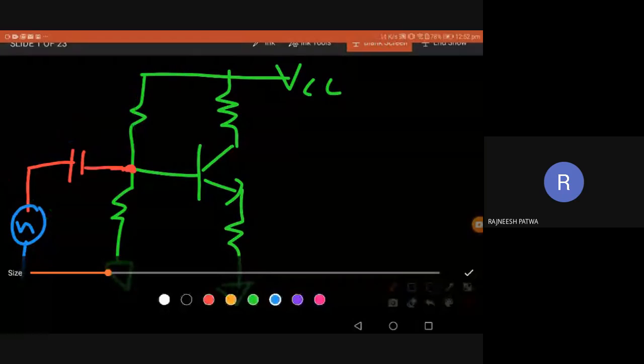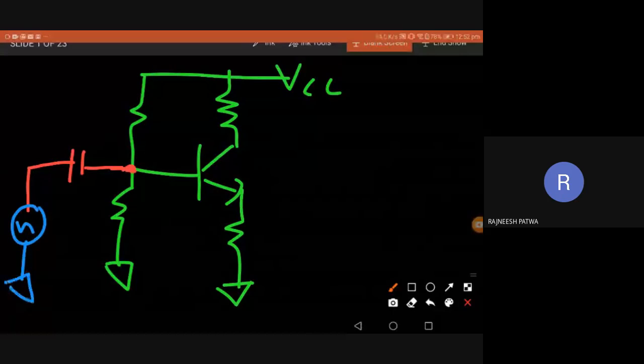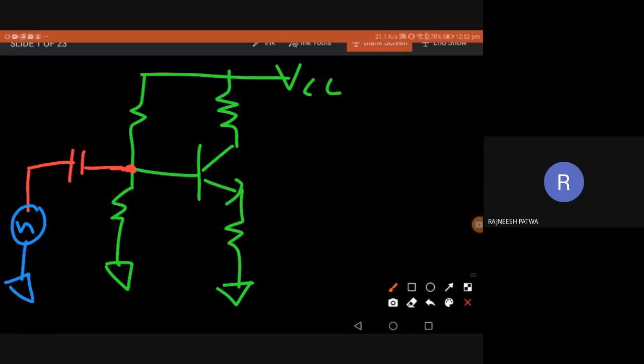Okay, so this coupling capacitor gives zero impedance to AC to come into the input of the amplifier, but it gives infinite impedance to the DC. Okay, you should remember that a capacitor is offering infinite impedance to the DC. Why? Because the DC frequency is zero. XC, the impedance of a capacitor, is XC equal to 1 by C omega, right? 1 by C omega. So the higher the frequency, the less impedance the capacitor offers. So for AC, the capacitor offers much less impedance than for DC.